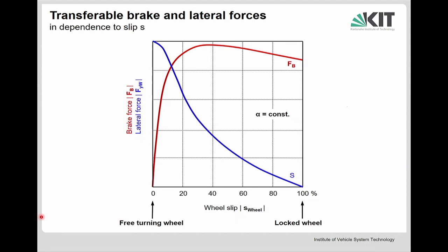And as you may remember, the actual needs depend on the friction coefficient between the tire and the road, and the friction coefficient depends on many parameters. So it was the temperature, the type of the road, the condition of the road, the weather conditions, and a lot of parameters from the tire. So what rubber compound is used and what tread pattern and things like that.